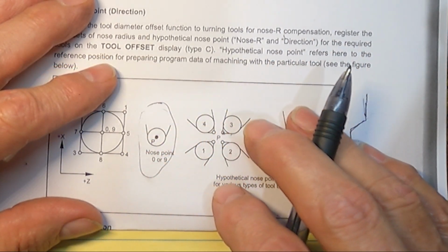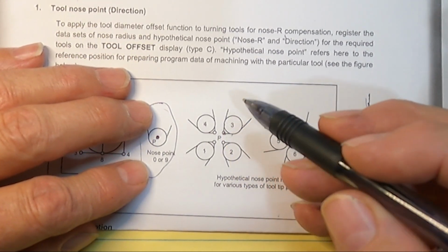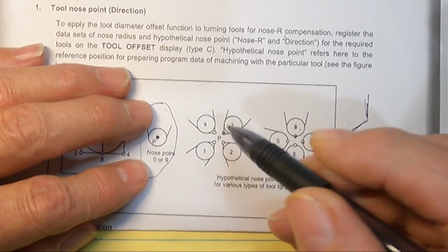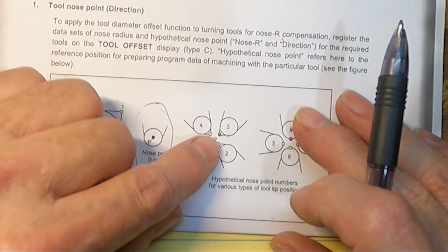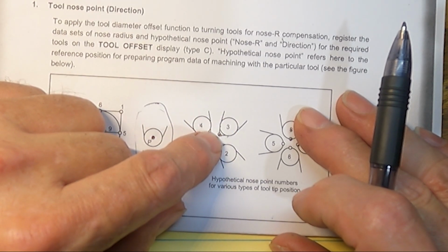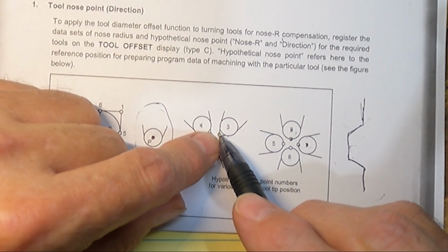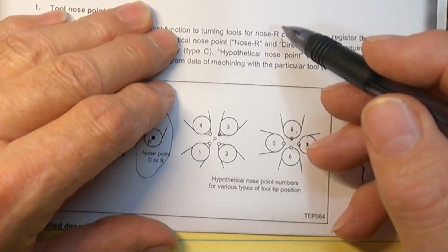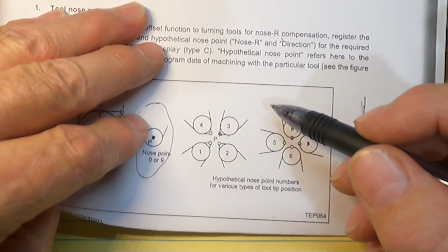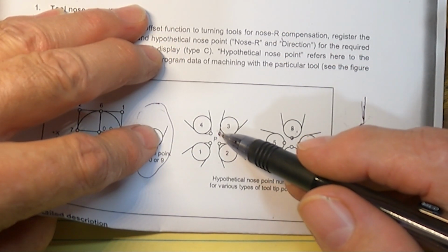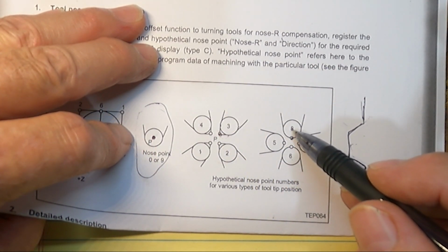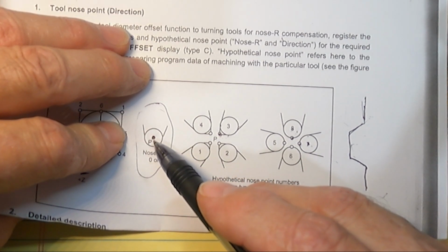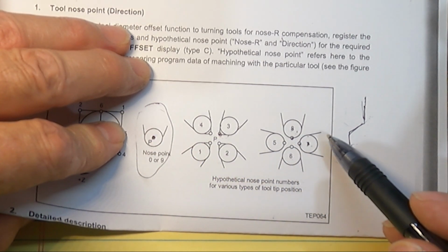But you can run all your programs without using tip comp, and say you set in your CAM software, you set your OD tool to the tip here, then you can process it and it'll work fine. The only thing is you have to make sure that you're setting this on your machine exactly the same way you set it in your CAM software. This is important, and I'll show you the CAM software in a second here, and you'll see the differences in the tool path between this setting and perhaps one of these other settings here. The CAM software, I don't know, it might have this setting as well in it. I have to see.